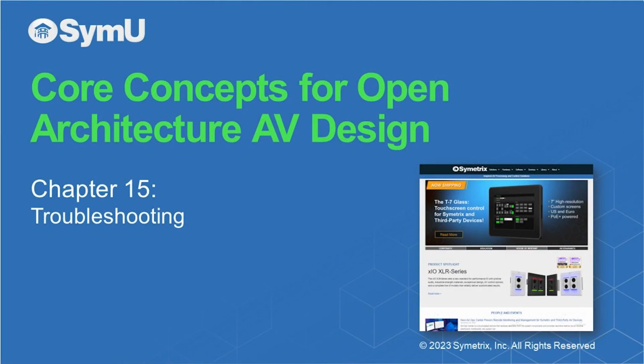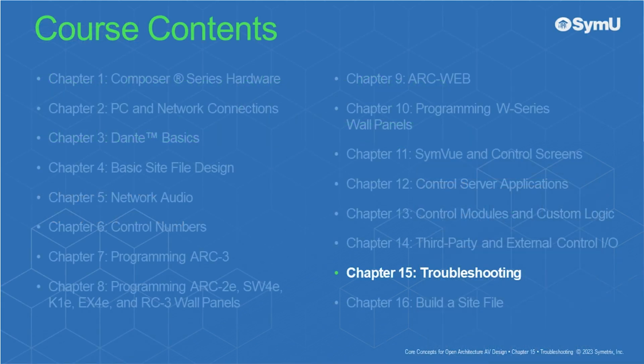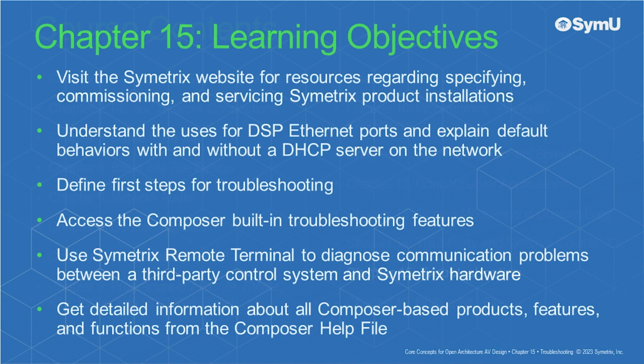Core Concepts for Open Architecture AV Design, Chapter 15. Troubleshooting. Our learning objectives are to visit the Symetrix website for resources regarding specifying, commissioning, and servicing Symetrix product installations, understand the uses for DSP Ethernet ports, and explain default behaviors with and without a DHCP server on the network.